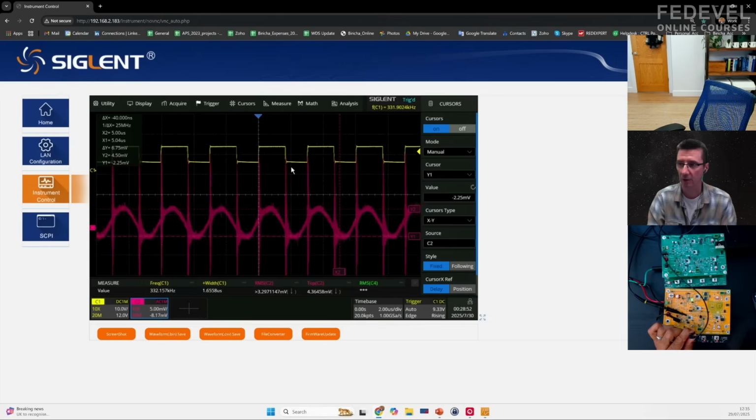So basically, the value of the capacitor on this power supply for this load is fine, because the noise, the ripple is very low. In this particular one, yes. I mean, it has been designed to meet a certain specification, right? Okay. Perfect. So what is the difference between the ripple on ceramic capacitor and the electrolytic?